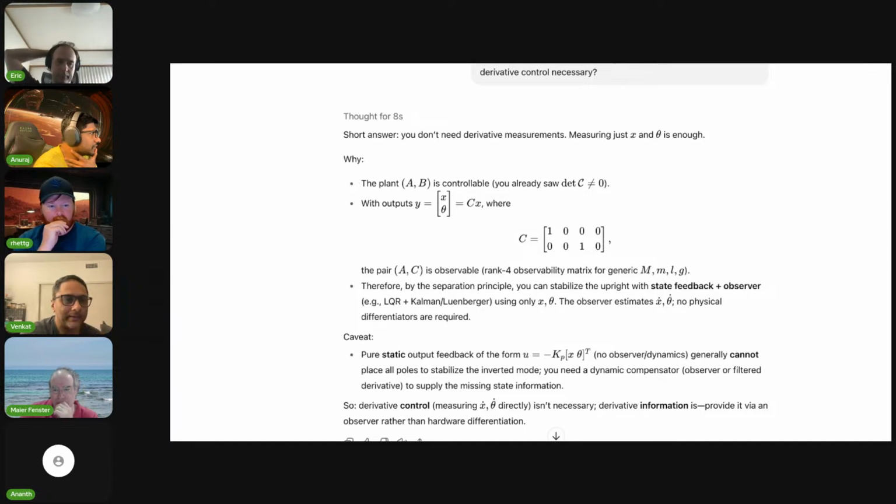Right? Yeah. So you either have to know the dynamics relating the various variables, which allow you to compute it in a numerical way. So, for example, if you have a position and there's noise in the system and you numerically differentiate it, it'll amplify the noise. So it may not actually be usable, right? So you need both the physics to connect the variables you want to observe, and you want them to be noise-free and computable. So there's a computability criterion as well. But there's an example, I think, later on.